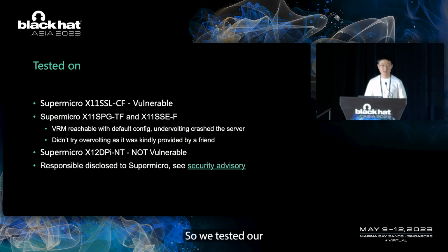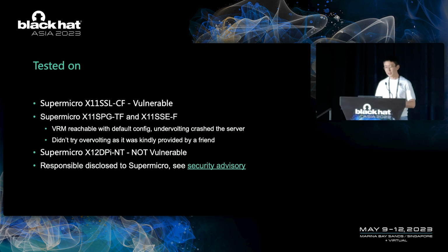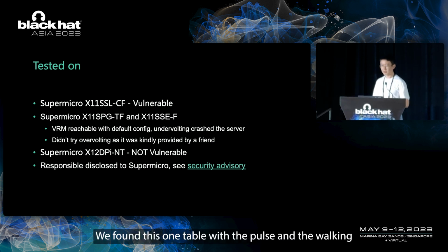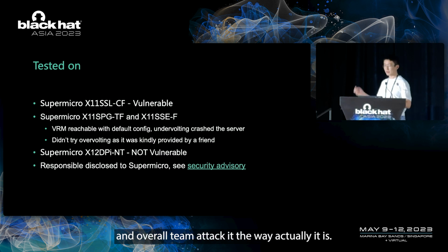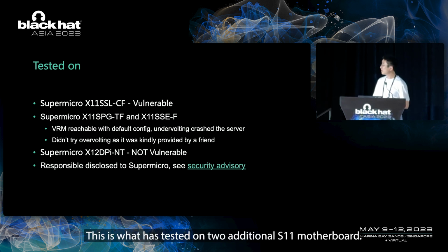So we tested our work on the Supermicro X11 motherboard. The first one is the motherboard we bought. We found this vulnerable. We did both undervolting and overvolting attacks on it, and we actually destroyed 2 CPUs. We also tested on 2 additional X11 motherboards.